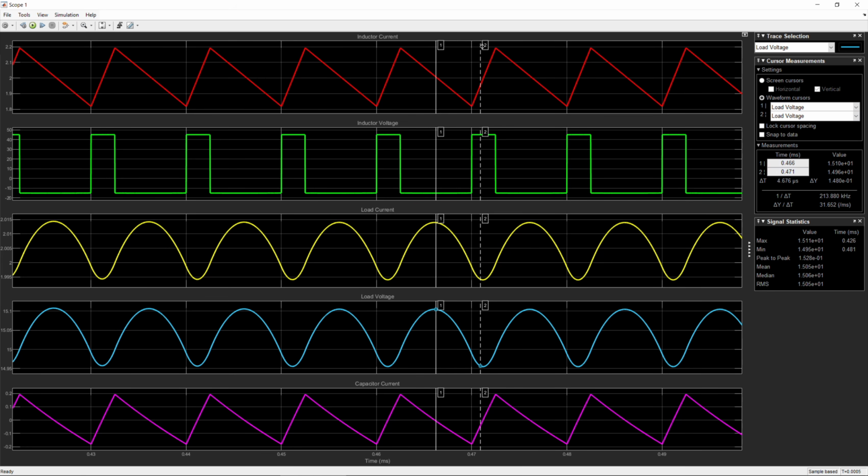So if I go down, you see here, label 2 and label 1, the peak here will be approximately, let's say, 0.15 volts, but you see the peak value is a little bit larger. It is then 0.15, let's say 3, so 153 millivolts. So there's a small error compared to our calculation, so it is very close to what we wanted.